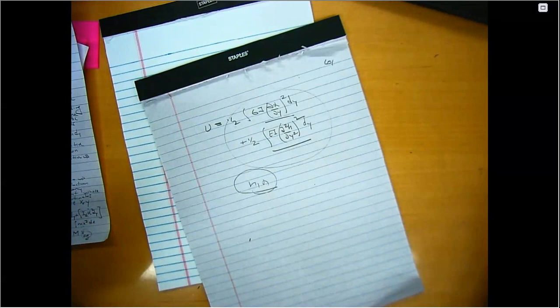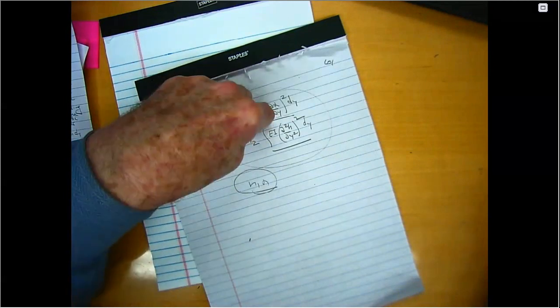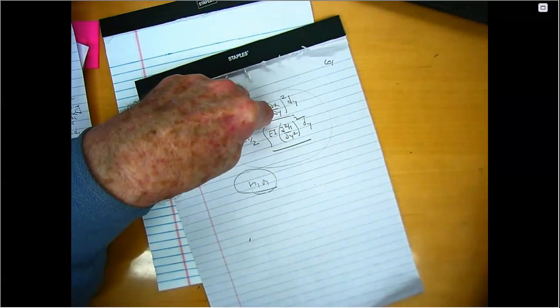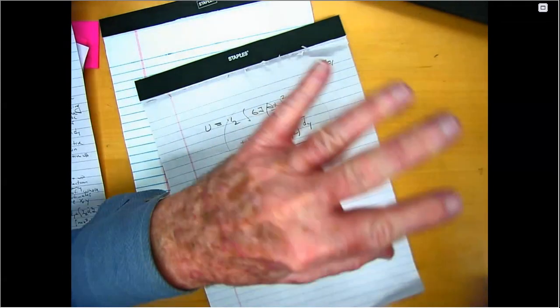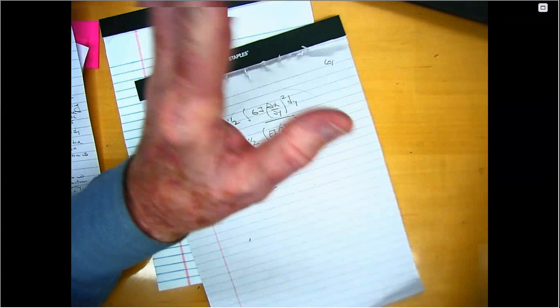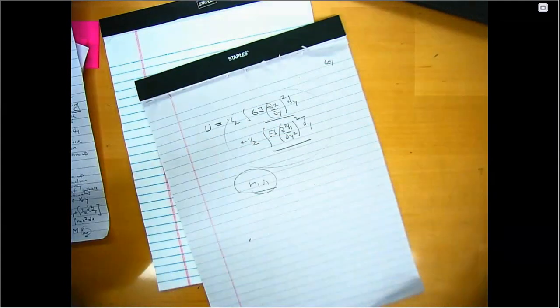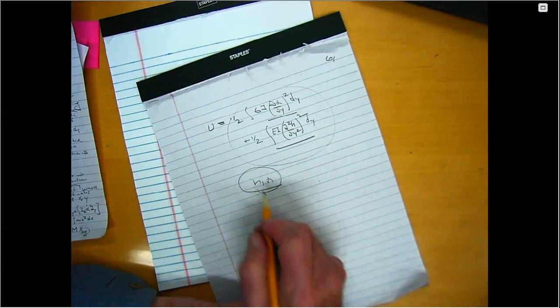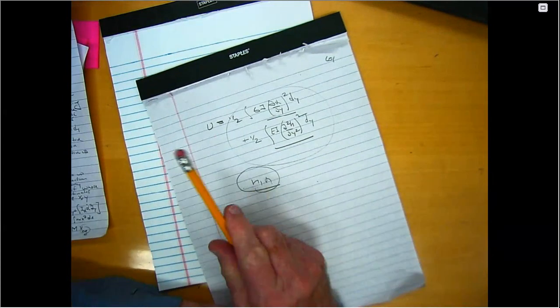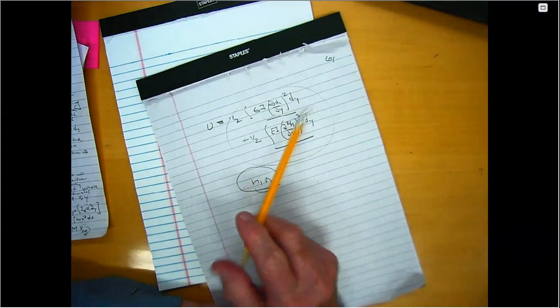Because the expressions for kinetic and potential energy are quadratic in h and alpha. As long as they're quadratic, I know I'm going to end up with linear equations, no matter how many time and spatial derivatives there are. Right? So I'll end up with two linear partial differential equations because both h and alpha depend on y and time.